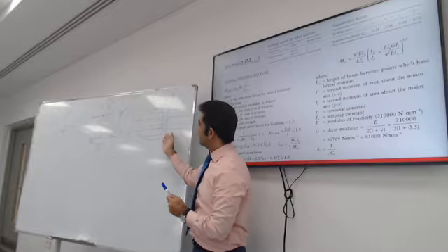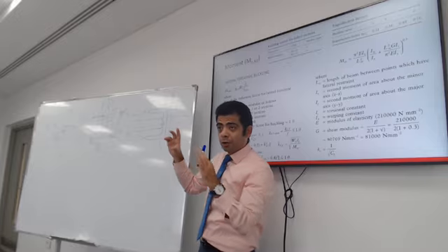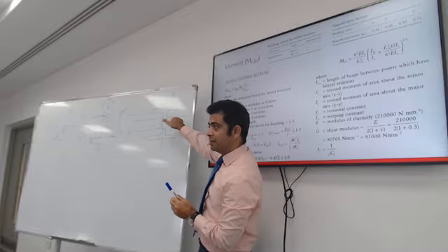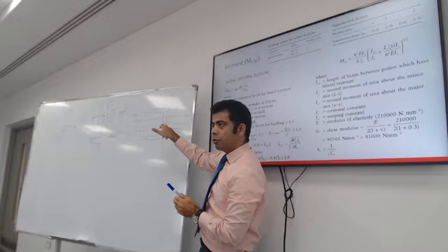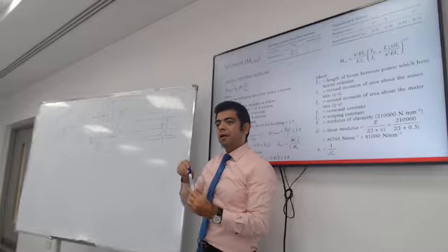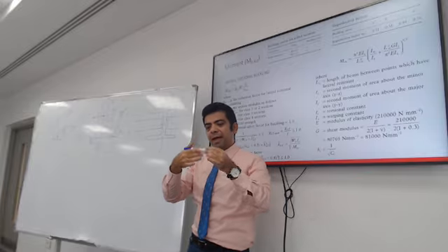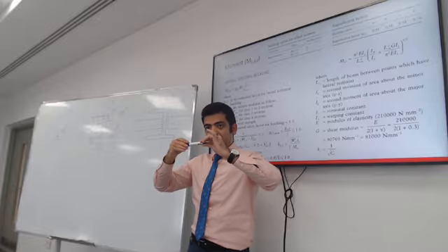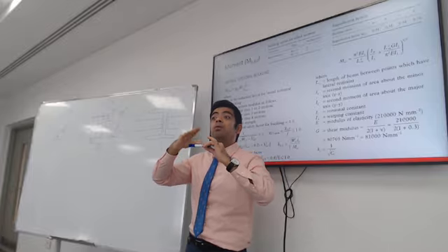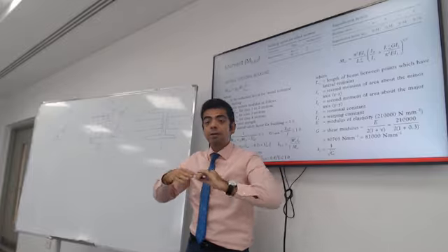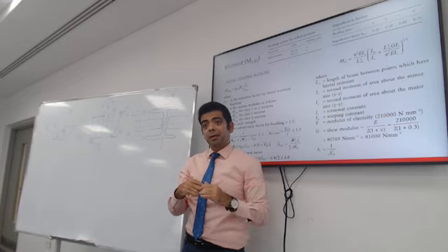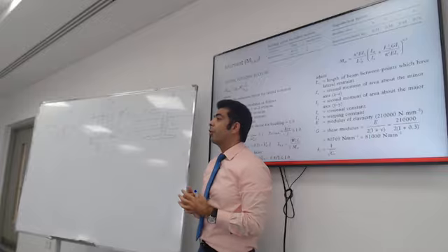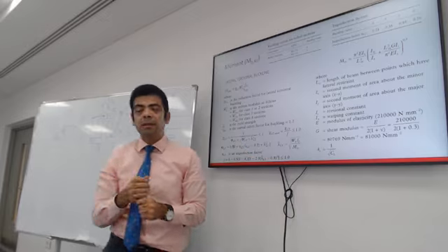Do you see how this section, when you go in the commercial tables, will have 2 W's? W about X and W about Y. One of them is stronger than the other. If you have this beam, it's going to deflect less in the strong moment of inertia. If you move it 90 degrees, with the weaker moment of inertia, you get more deflection and more buckling. The section is weaker or less stiff in these directions.